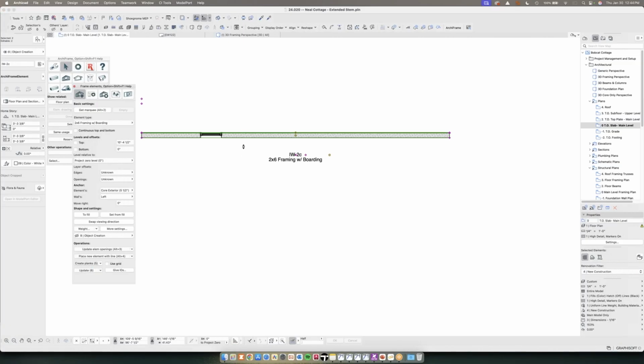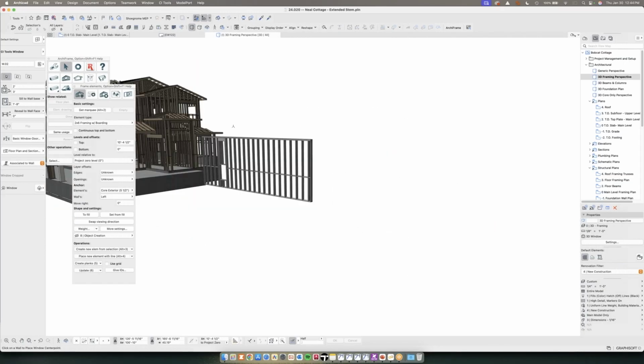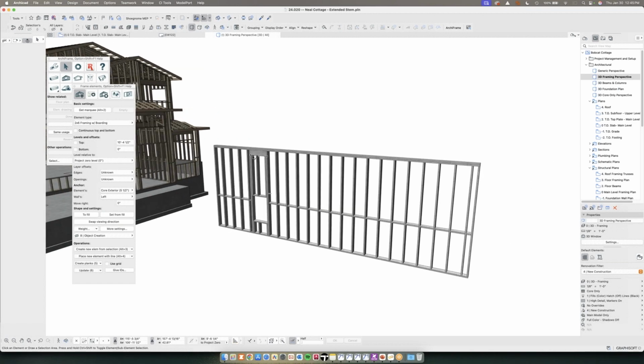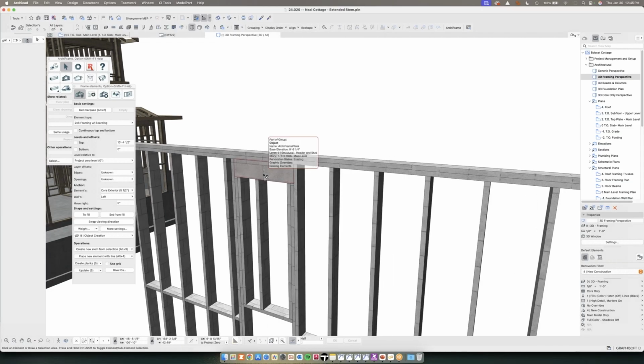It buffers. And again, I do this typically, when I do a building, for example, I will draw the element over every wall, and then I will highlight every wall, and I put the framing on every wall. So now if I go back to my 3D framing perspective, that wall is detailed out, it's highlighted. I have in my settings menu, which ArchiFrame did help me set up, I like my headers at the top of the wall under the top plate, and it frames down.